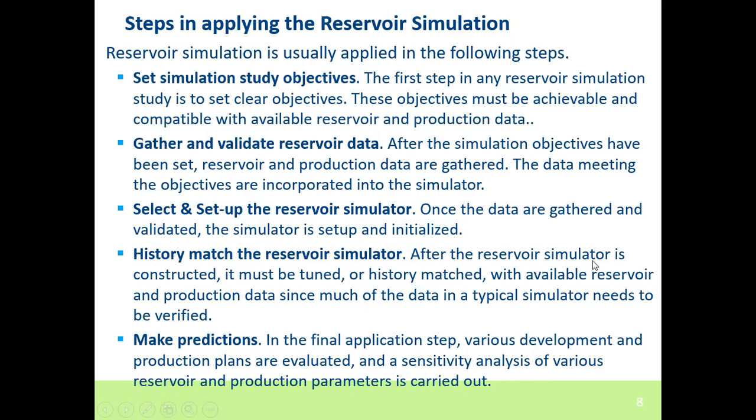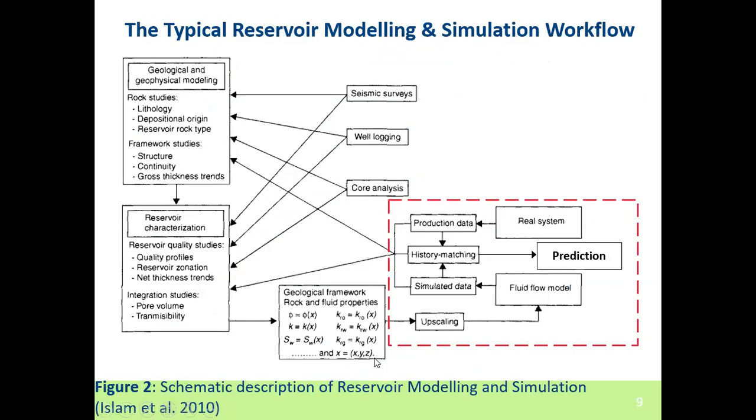Since after the reservoir simulator is constructed or selected, as the case may be, the model must be tuned or history matched to available reservoir and production data, since much of the data in the typical simulator needs to be verified. And it's the history matched model that is basically used in making predictions.